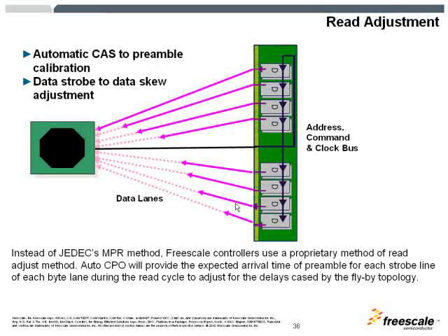As you can see, the commands would arrive at the first DRAMs, and then as they propagate through the line, they will reach the last SDRAM. The command will arrive at each of these SDRAMs at different timings, and they would send their information on the data bus at different times.